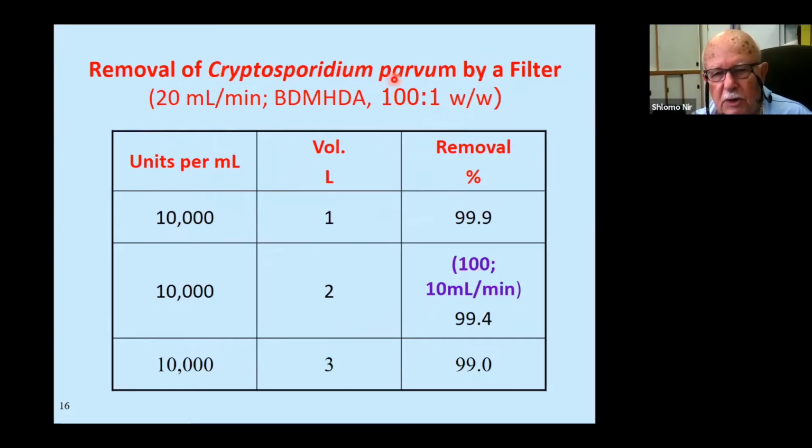The Cryptosporidium parvum in water can cause serious intestine disease and sometimes death, and epidemic in lakes, depending for drinking water on the lake water. This parasite is insensitive to chlorine, and therefore we suggest here a very efficient removal.